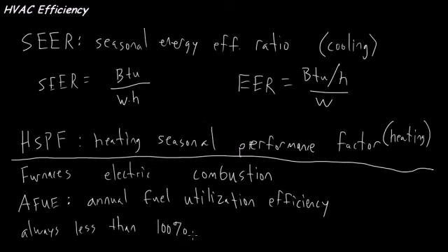We're burning some chemical, most of that heat makes it into the space where it should go, and some of it does not. Some of it just goes up through the flue, either because of incomplete combustion or various other losses. So in practice, furnace efficiencies are typically 70% for older ones, to 97% for newer ones, which can be very high.